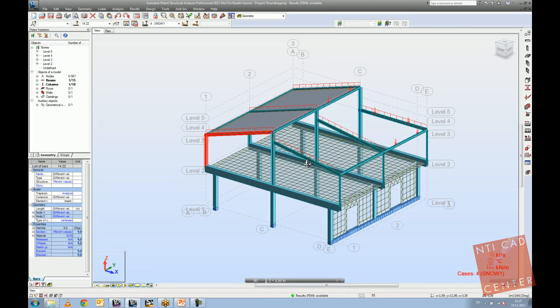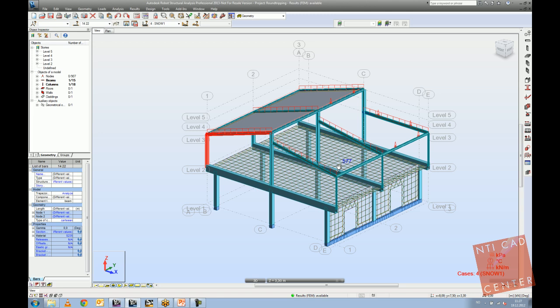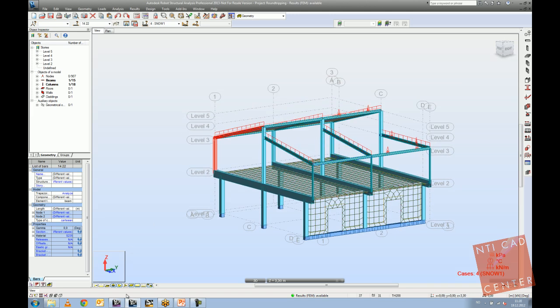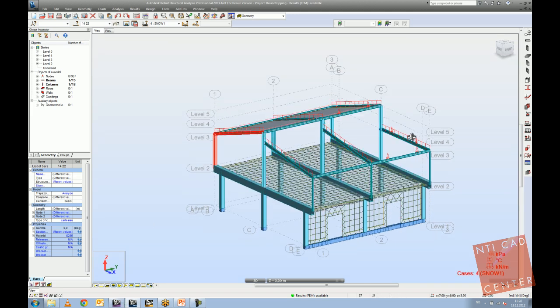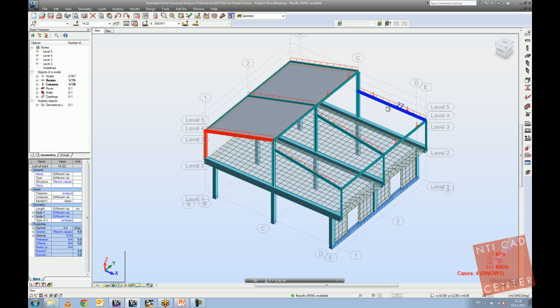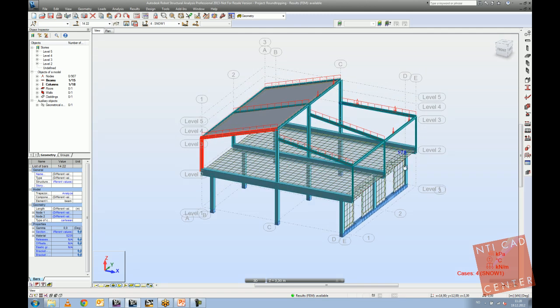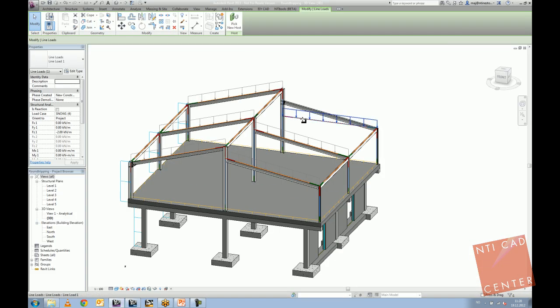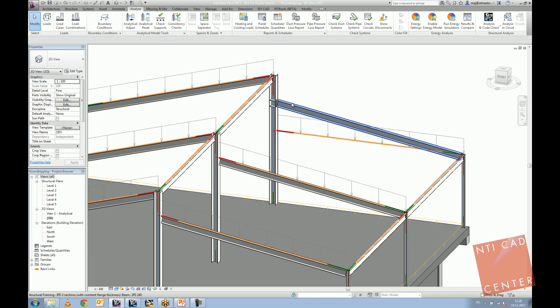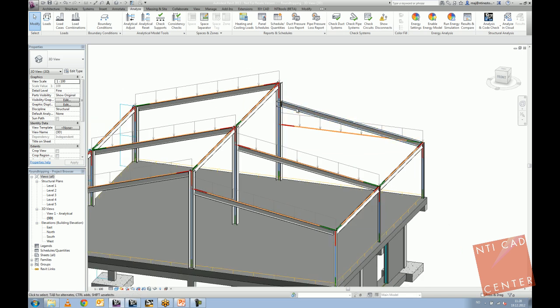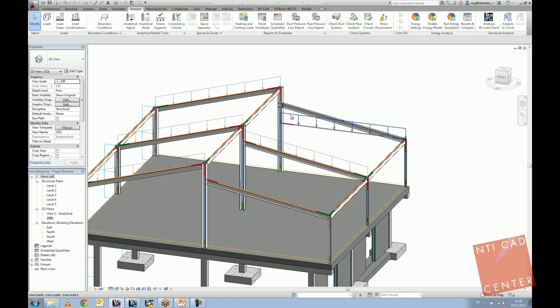For example, if I would add a new beam, this beam would be imported into Revit. But if I modify something existing, for example, if I move a slab slightly or move a beam slightly somewhere, it actually updates just the analytical model. So your geometry stays intact actually. The geometry is where it is. Of course, you will get this warning for coordination that the elements have a distance now bigger than something.